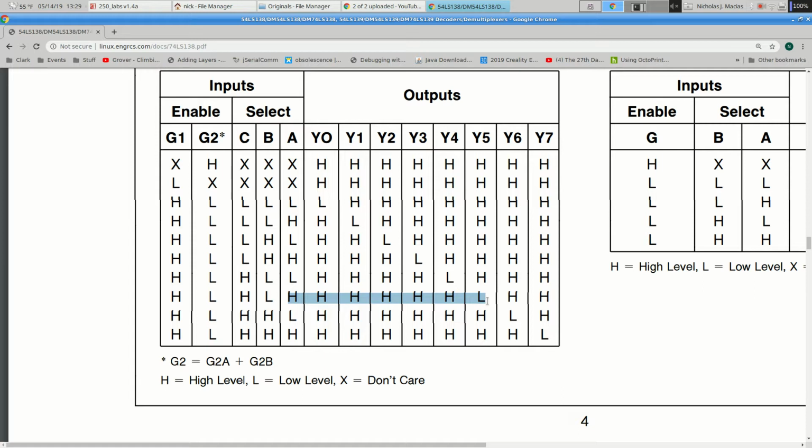What's the other option? Flip the LED and connect it to power. So run your LED backwards into these outputs, connect the other end through a 1K resistor to VCC, and now, what you know from your previous labs, if the output is 0, the LED will be on. If the output is high, the LED will be off. And so that's going to do exactly what you want. So that's the next trick, right? Put your LEDs backwards, save on 2 chips and a bunch of wires.